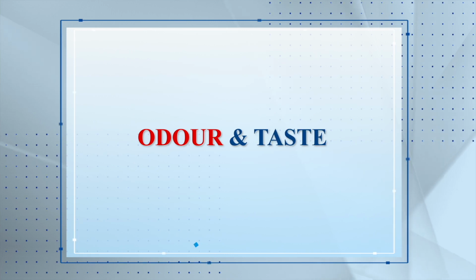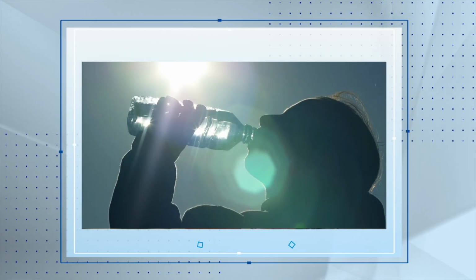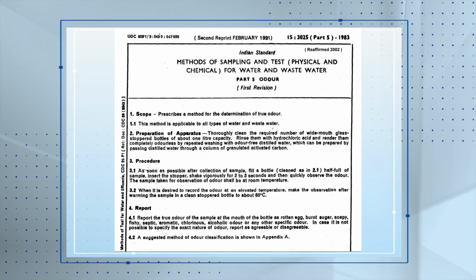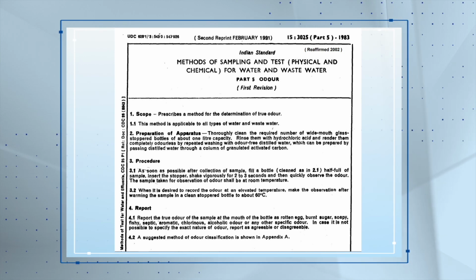Odor and taste. Water is expected to be odorless and tasteless. However, both these characteristics are subjective in nature, as different consumers can have different perceptions on drinking the same water. Therefore, there is a need for standardized methods of tests even for these simple characteristics, which are in the form of a panel of tasters, to arrive at generally acceptable levels of quality.